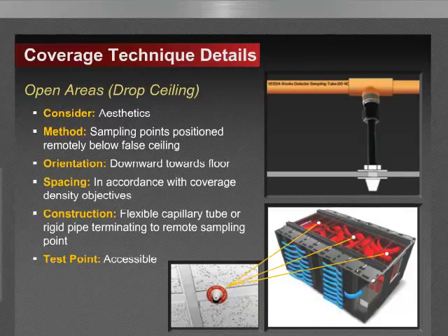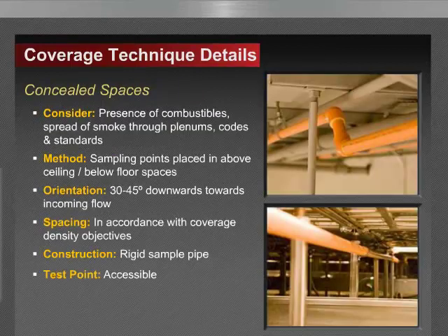All right, that brings us to discussion about concealed spaces, such as raised floors and sometimes ceiling voids of IT communication facilities, which may contain large quantities of electrical cabling. In such cases, it is important these areas are protected. When used for return and supply plenums, the presence of high airflows in these concealed spaces will lead to rapid spread of fire and smoke.